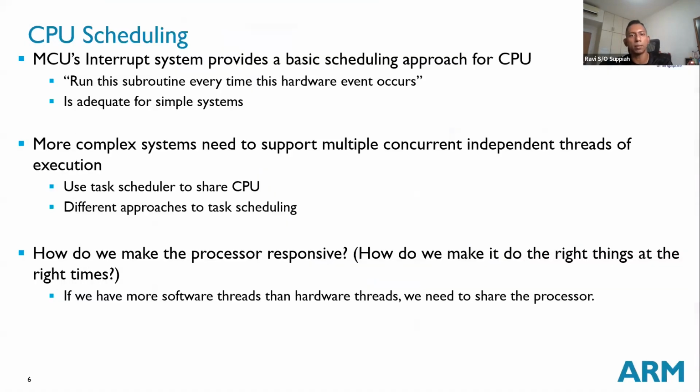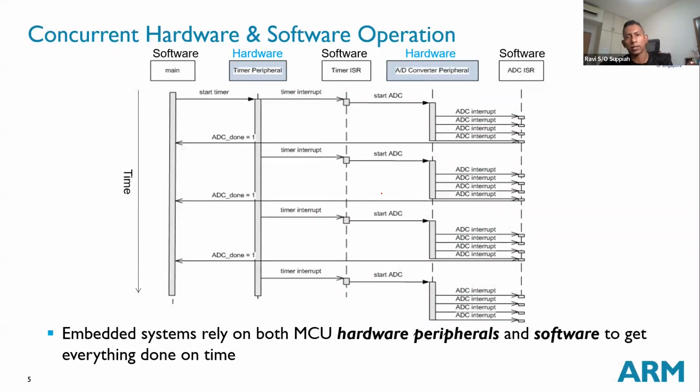This is an example we saw last lesson. I will not go through this again, but basically by configuring some hardware interrupts to happen at some periodic interval, certain things can always happen in a real-time manner while you have a main loop that is running at the back end. So this already allows us to have some level of concurrency. That is good.